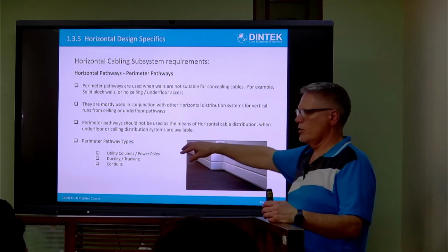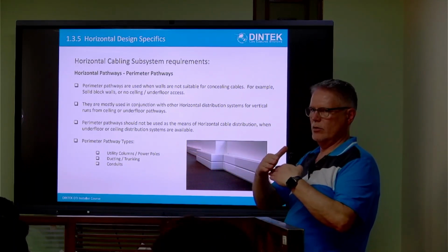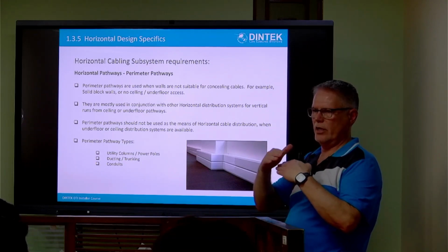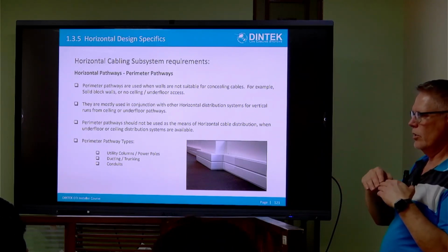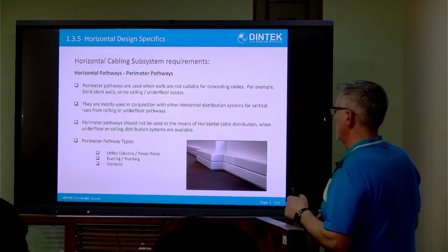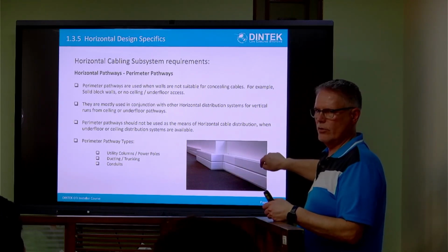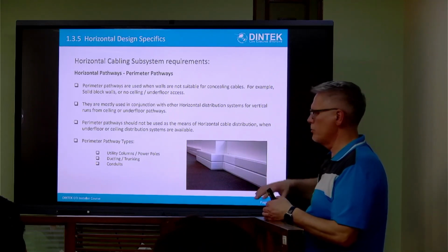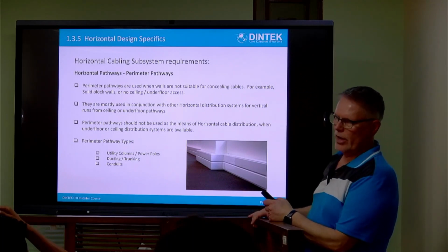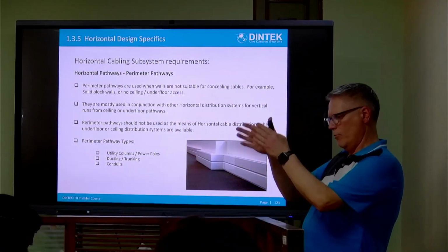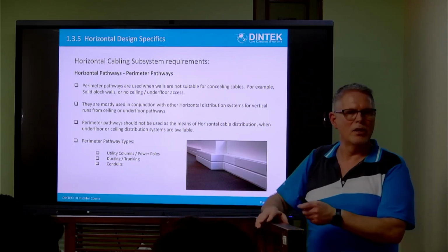Mainly because this could be over a certain distance, and we've got electrical cables and data cables running in that trunking, even though they're separated. If it's a plastic trunking, we're going to get interference between the two, because it's quite close proximity. If you're running in steel trunking, that trunking is going to be electrically earthed, so you don't get that interference. If it's just ducting that's coming down the wall, even if your electrical and power cables are running close to each other, they're not going to introduce too much interference.